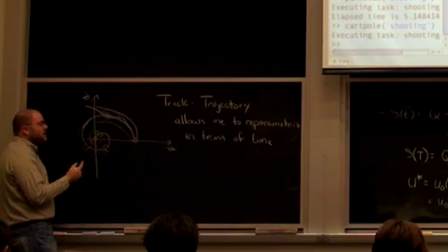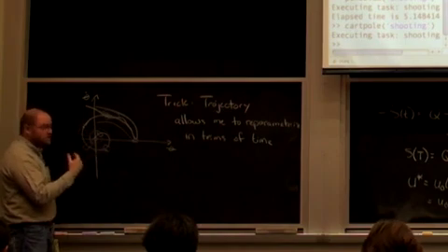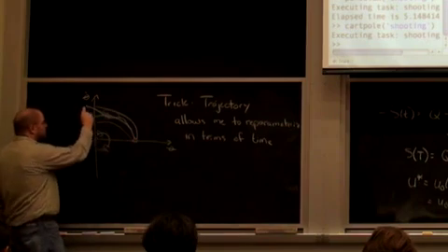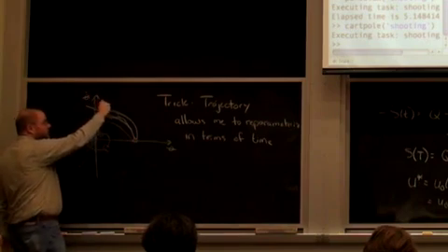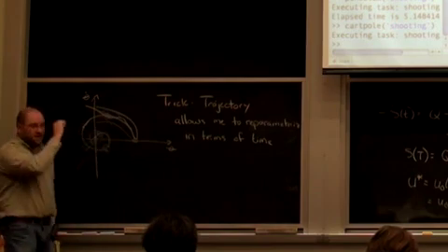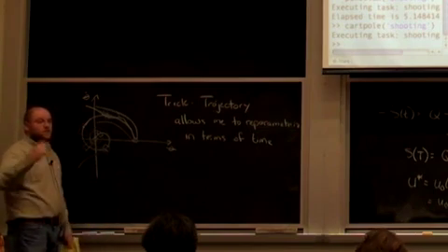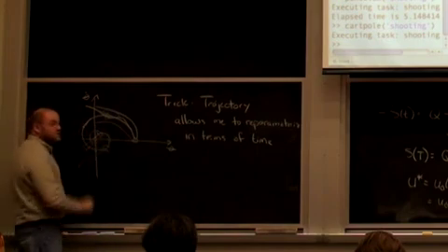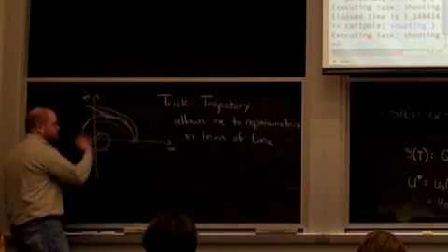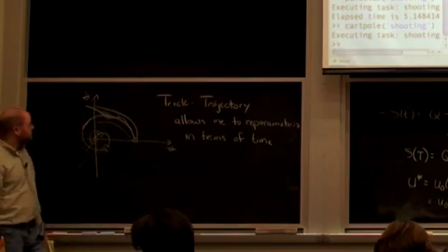The only price you pay is if your torque is smaller. If you're penalizing torque use higher, then you might shrink your basin of attraction. It might be that because it's trying to use less torque, it will not overcome the nonlinearities. Okay, but in the neighborhood of the trajectory, you can get these very elegant solutions, which look like minimal energy kind of solutions for the nonlinear problem in the vicinity of these trajectories. So one of the ideas we'll talk about later is how do you design the minimal set of trajectories which, if you use these controllers, sort of do the right thing in a lot of places.